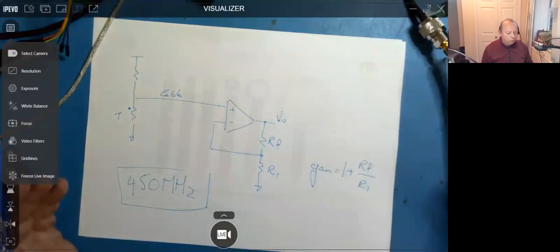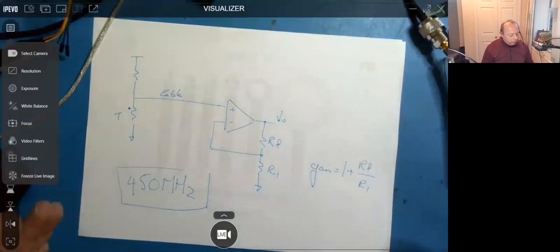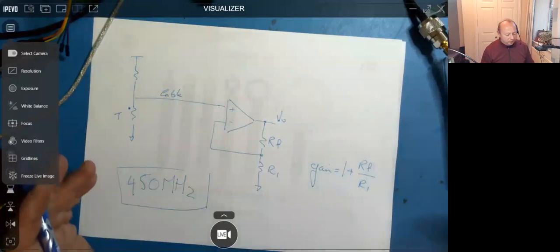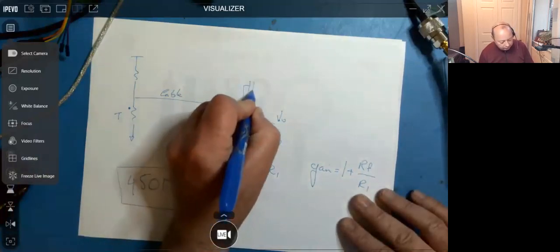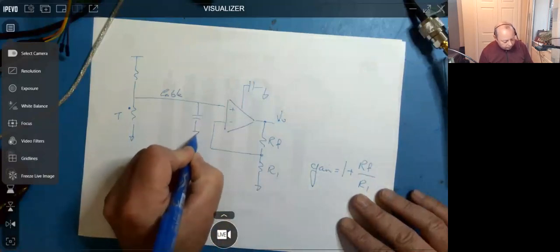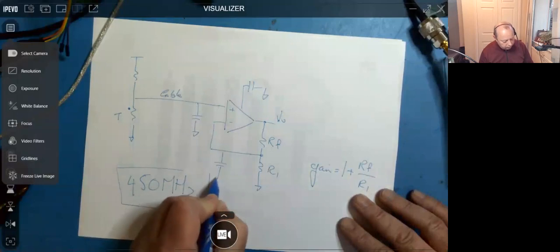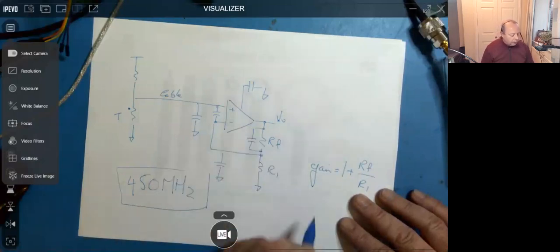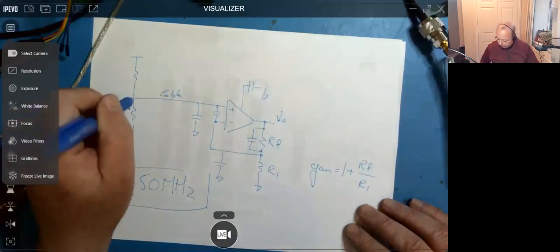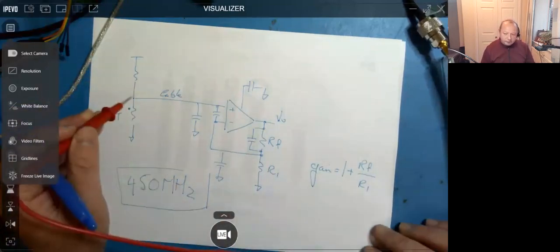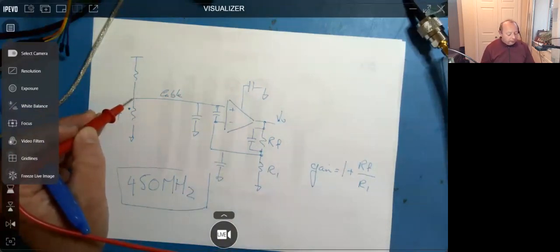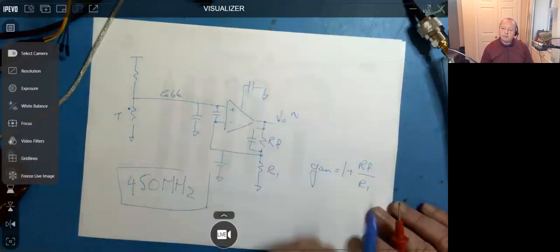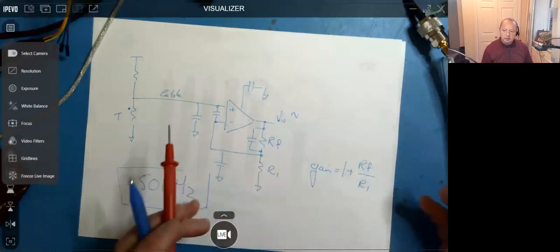And there's nothing here to suggest why that would happen. So what I managed to work out, when you start trying to fix these problems, you put capacitors everywhere, a little bit like as you were just saying, William. So I added them here and here, and I put one here, I put one here, and I put one across here as well, can you believe? And I injected the noise with the probe tip right here, using the generator I've got here. And yeah, I could see just a little bit of an influence. It wasn't anything like going to the EMC site, but I could see just a little bit of an influence going on here. But at other frequencies, it just wouldn't happen.